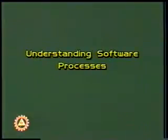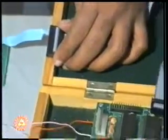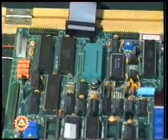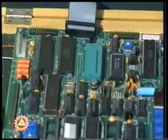We have identified the hardware components and the software processes required for the system. Now, we have to integrate these two. Let us take an example to describe the integration process. In this particular example, there is a keyboard, and in the software we have a delay subroutine. This software delay subroutine is doing the job of key debouncing.